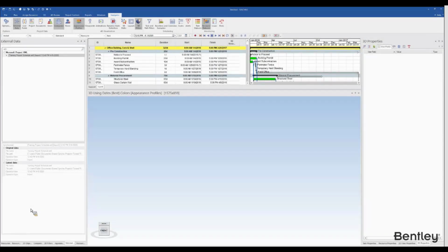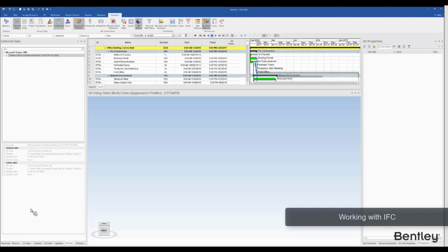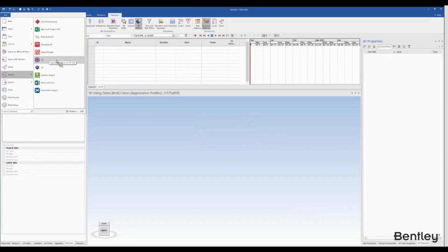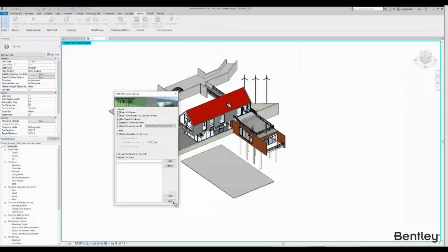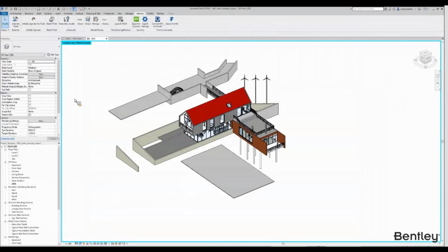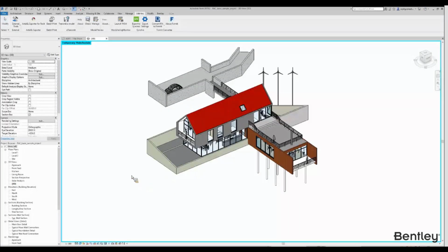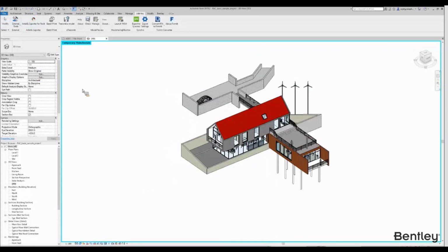All right. For IFC, usually we have typically two workflows. One is that we can import directly by going to File, Import, and choose IFC file. And another choice is that we import IFC files to Navisworks and export those models to an SPX file and then import to Synchro. So one important thing regarding IFC workflow is it's a bit different from any other workflow, if you're using SPX or a DWFX.